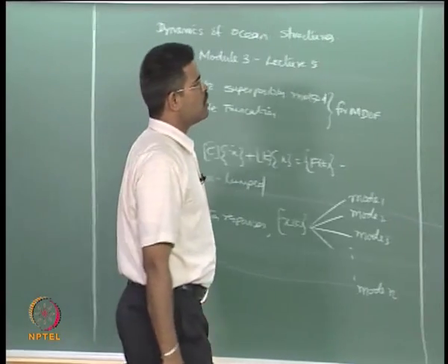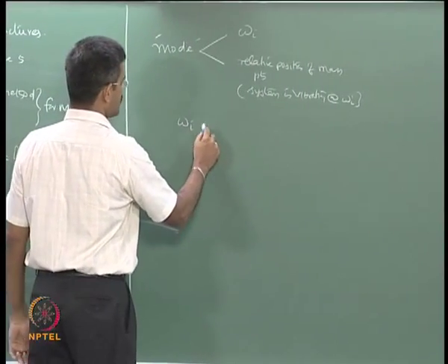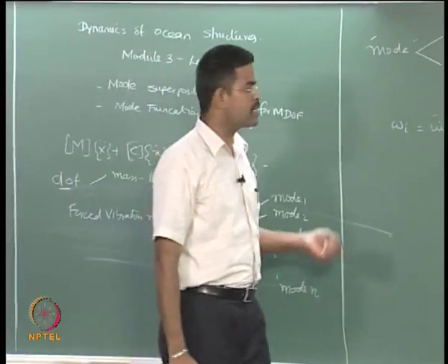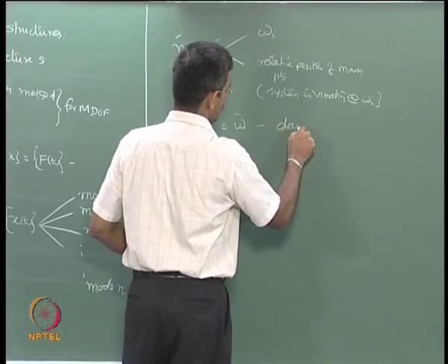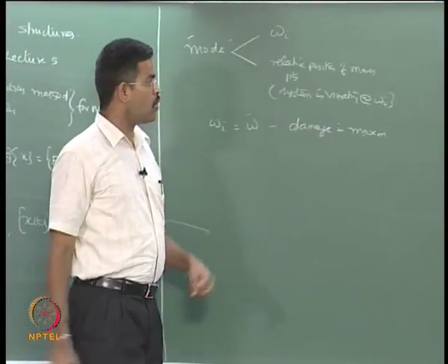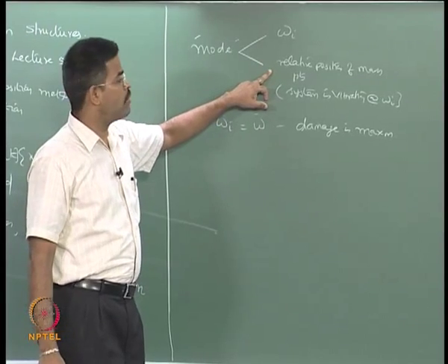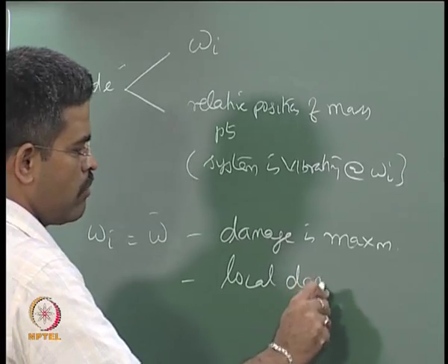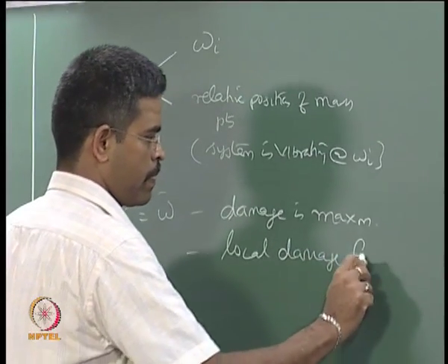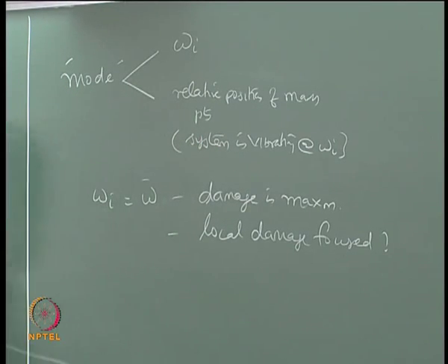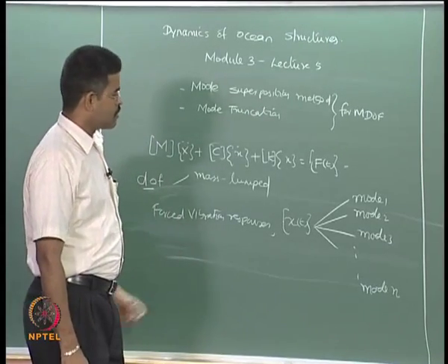So, I can easily find out if this frequency matches my excitation frequency. I can always expect that the damage is going to be maximum, and by knowing the mode shape I can know where the local damage will be focused, because I know the relative position of the mass movement. So, the response is always contributed from different modes.